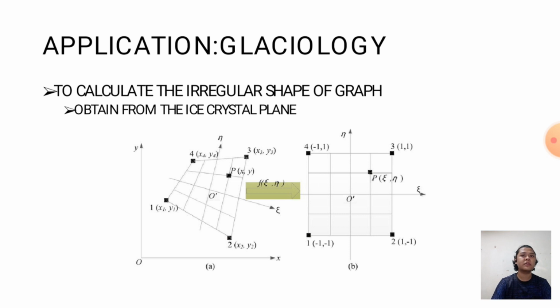extremely intricate boundary shapes. Although the employment of the triangular element may always suit difficult borders, the element precision is generally low. So one of the most frequent techniques for dealing with irregular boundary shapes with improved precision is the employment of the high order element, with the isoparametric formulation being the most widely employed at the moment.